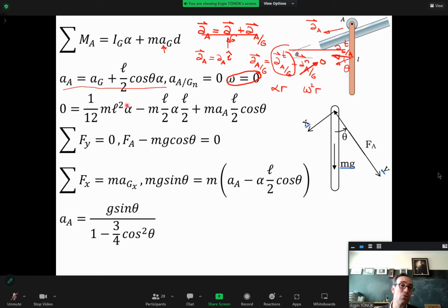So here, actually taking moment about point A does not provide, I would say, much useful answer, because finding the reaction force is not something difficult, okay? So you could also use mg is equal to ig alpha. You can directly get an expression for alpha from mg equals ig alpha, and then you can substitute it into this expression and still get it, okay?